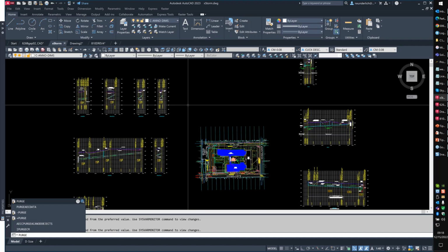And do regapps cause actions in your drawing to slow down? Yes. If I am in a drawing, and I have seen this a lot, Joseph, that has upwards of 70,000 registered applications, and I've seen drawings with 500,000, I can start a line command and it will literally think for 5 to 10 seconds before it will ask you to pick the start point. And then I'll click the start point and then it will wait 5 to 10 seconds for the second point.